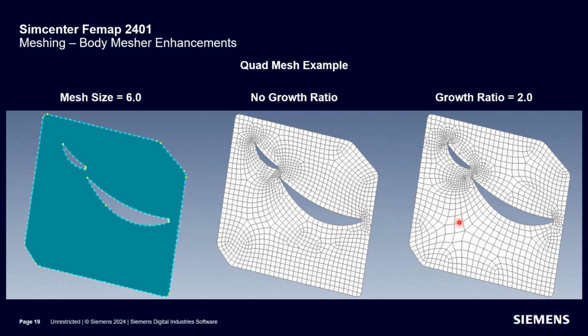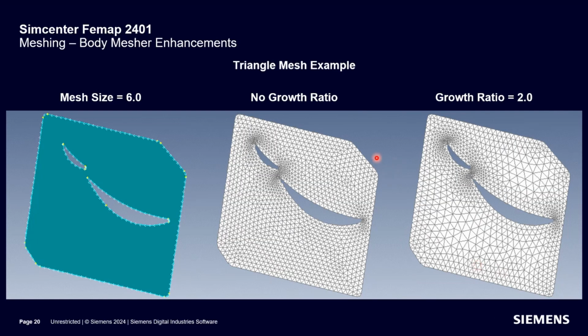And this option is available under solids too, and that's how I'm familiar with it. So it looks like they're just extending that to also work for plates. And you can see here, you have the same thing available for a tet or a triangle mesh. You can see here the mesh size on this curve is the same as in the middle of this panel, whereas over here it actually gets to grow and you have a little bit less resolution where you normally don't need it, like you would on a high curvature or a sharp edge or something like that.